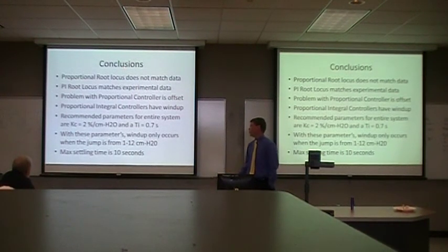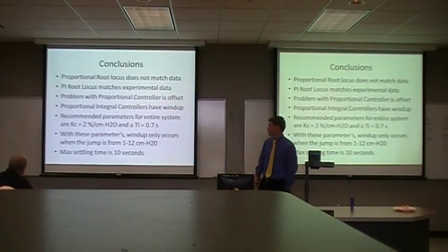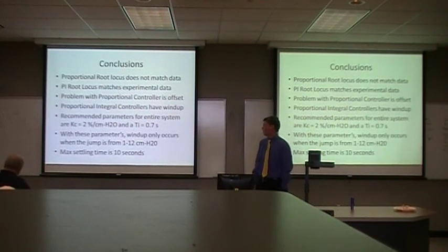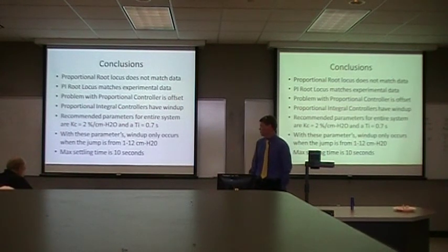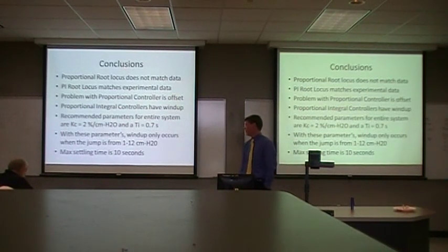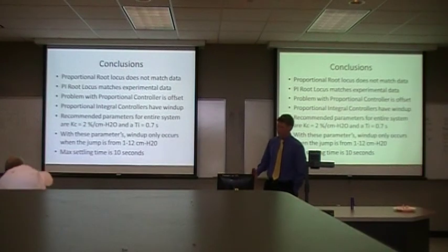The recommended parameters for this system were Kc equals 2% per centimeter H2O and tau I equals 0.7 seconds. With these parameters, wind-up only occurs whenever you're trying to go from 1 to 12 centimeters H2O. And the max settling time is 10 seconds.